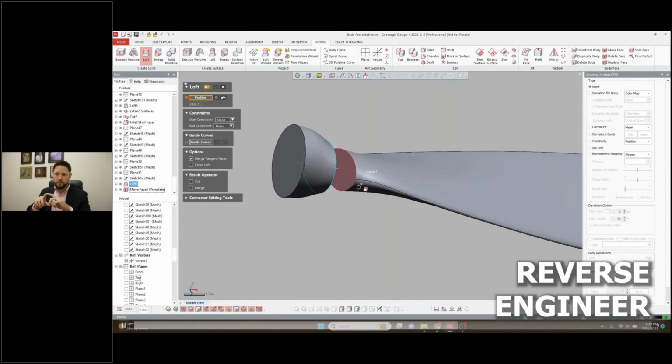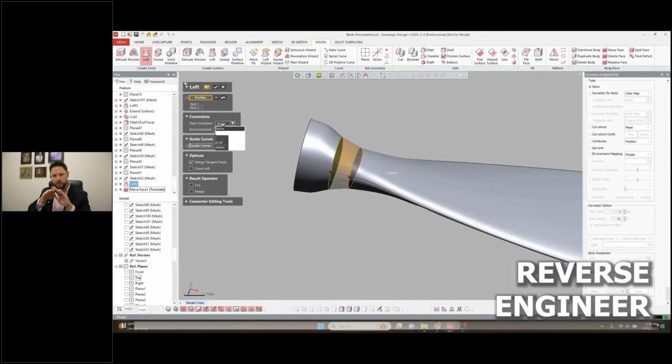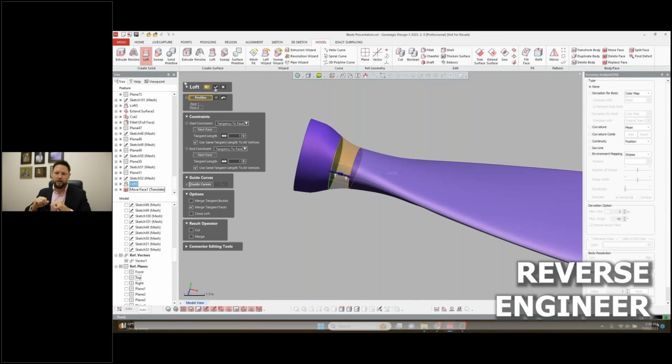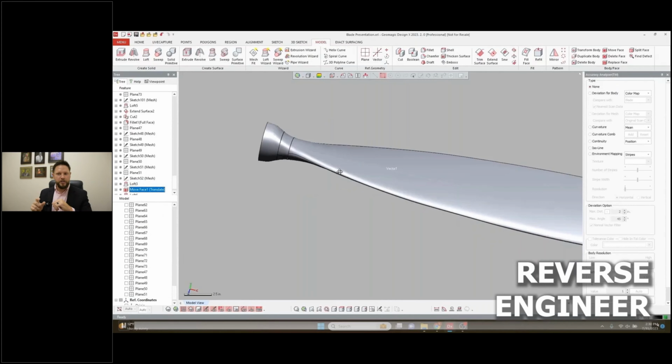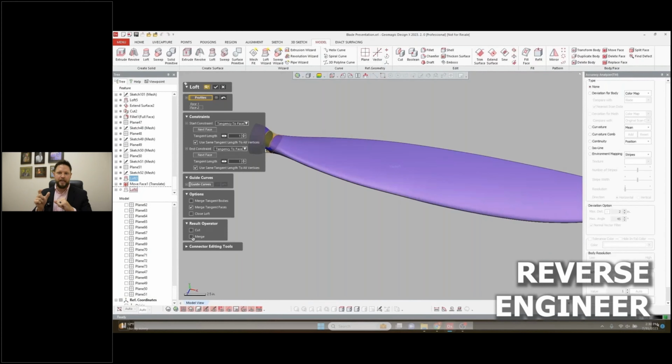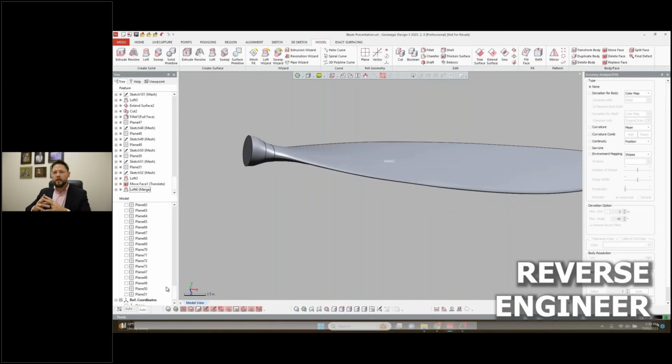And I'm going to make sure those surfaces are tangent so we get this really, really nice transition through here. So seamless transition, make sure that curvature looks good. If it doesn't quite match up, you can always add a new segment in between. You can draw guide curves on the mesh so we can ensure that we get that entire thing as accurate as possible and as clean as possible.